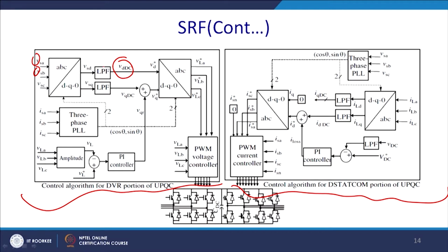And similarly with the Q we will have this value, and again we require to maintain the voltage sag. To do that, you will also sense the load voltages at the point of common coupling, and we will see what the amplitude of VL is, and accordingly we will check it against the reference voltage and feed it to the PI controller.